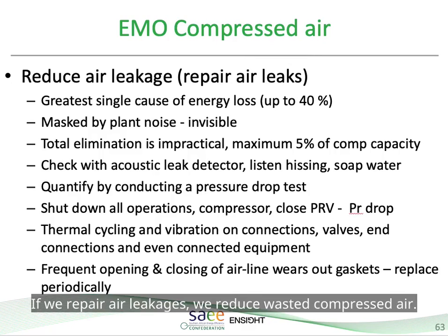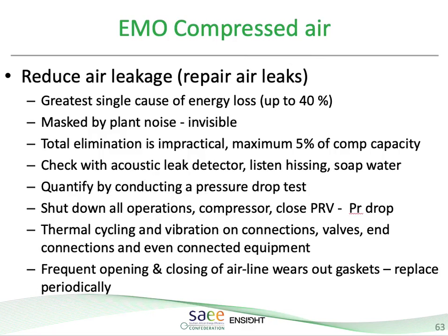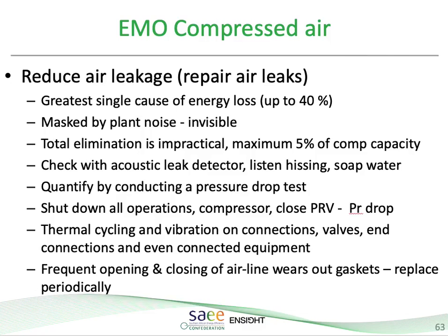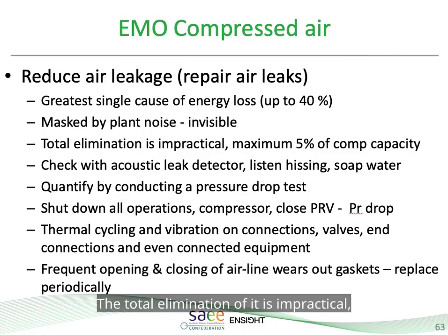If we repair air leakages, we reduce wasted compressed air. It is the greatest single cause of energy loss, up to 40%. It's masked by the plant noise, thus difficult to determine. The total elimination of it is impractical, but we can get to a maximum of 95% operational.